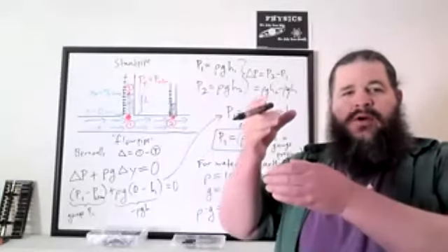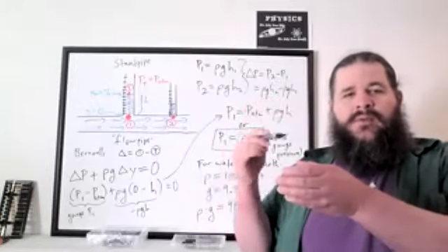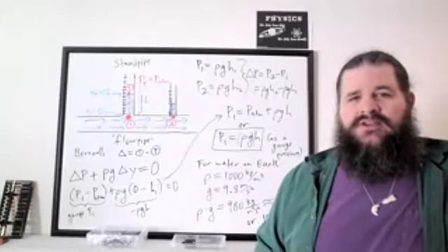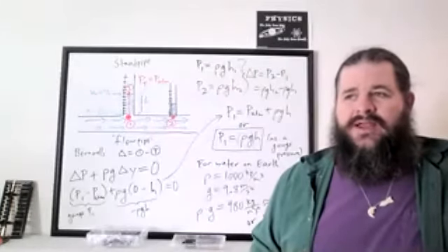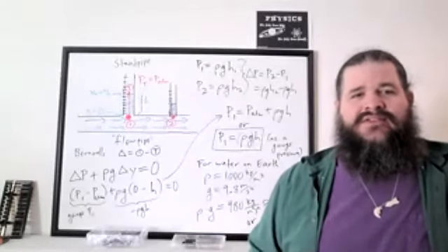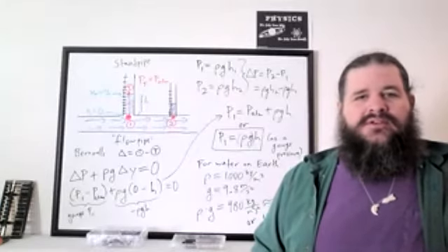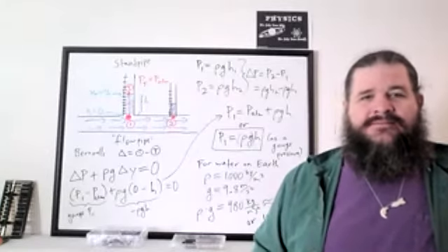Take a tube that water can flow up into, put a mark every centimeter, but instead of labeling them in centimeters, mark each of those with 10 pascals, 20 pascals, 30 pascals, etc. And you've got a pressure gauge. Any questions on this whole standpipe thing?